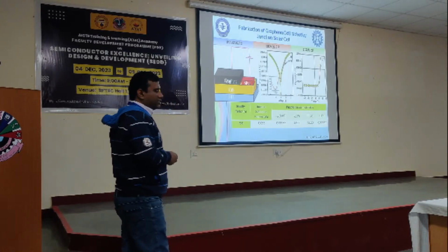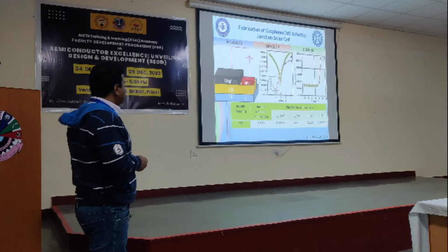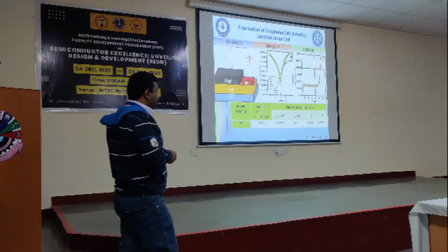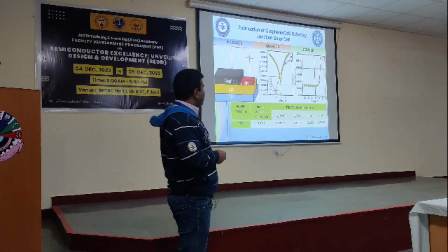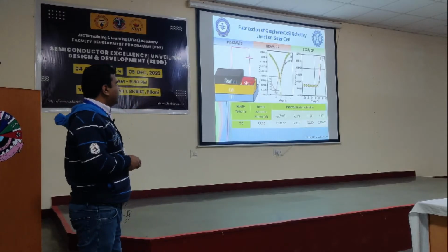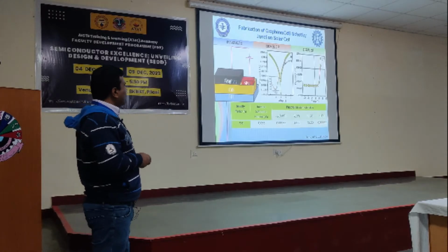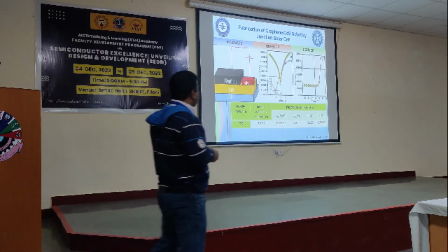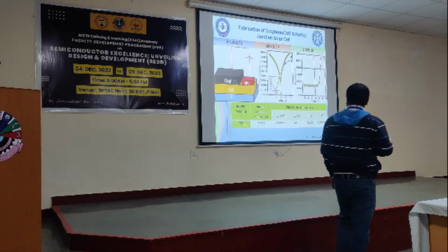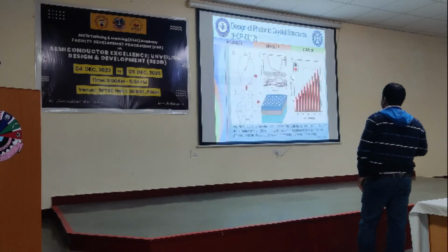Now this is another solar cell structure from another investigation related to solar cell devices, where we have used graphene with cadmium sulfide, to ensure the efficacy of cadmium sulfide as a protective layer. You see, in that case also you can get a fill factor of 56.5. The efficiency is quite low, but the current density and the reverse saturation current and ideality factor are also significant. That's why you can use this material in suitable applications in solar cell devices.